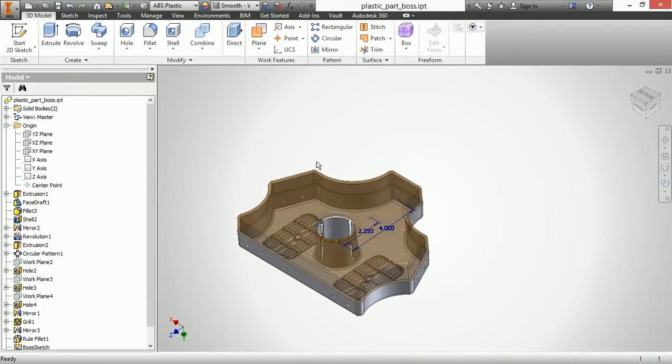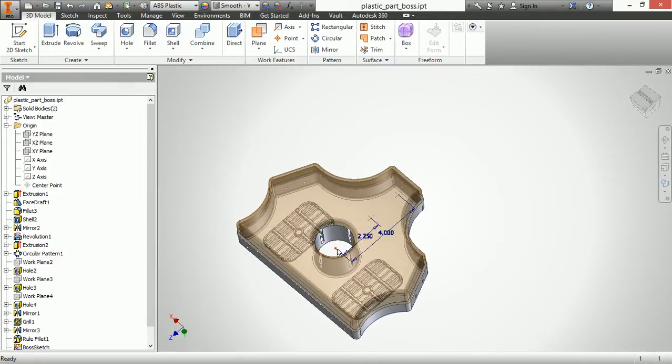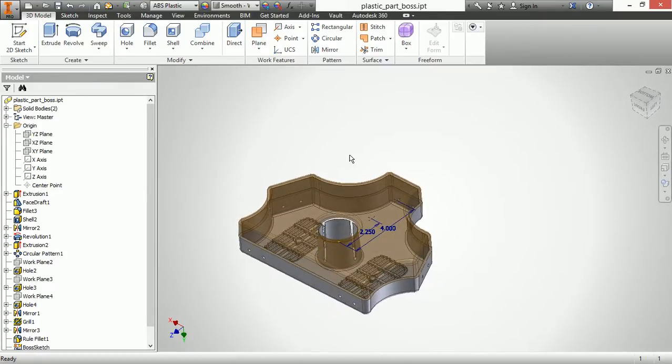And then inside of this, I have 2 points that have been drawn at 2 1/4 and 4 from the center of the part. Now the way that this works for the boss command is it uses that point, it can be 1 point, 2 points, it can be 10 points, to actually pick up as the starting point for the boss. Now when you build the boss, you have the option to have it build towards one of the 2 solids you have in this particular case.